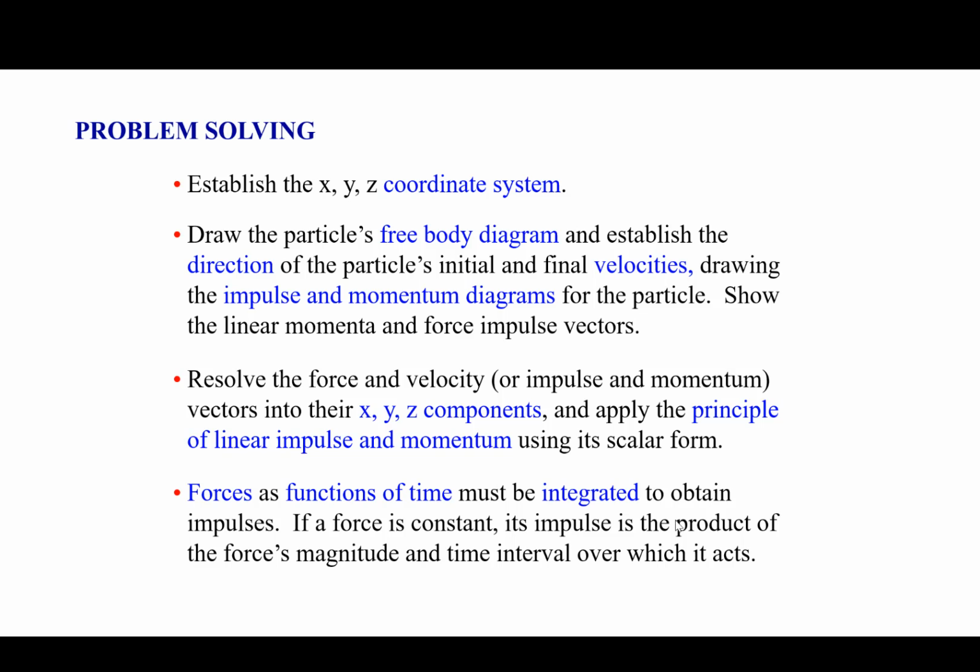We want to draw our free body diagram. We want to write the information that we know. And we may want to look at impulse and momentum diagrams. We'll talk about that in just a second. We may want to look at how this is going to sequence through, and we'll talk about that as we go through here. We want to resolve the force and velocity into our x, y, and z components, or our r and theta components if we're in that angular situation. And then we're going to use our principles of linear impulse and momentum to help us out. And then we want to look at our forces as a function of time.